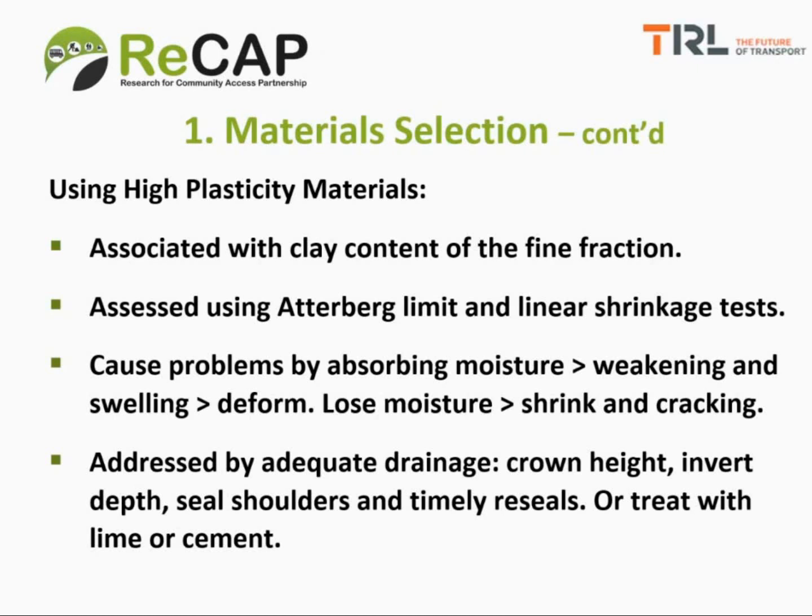Coupled with that is the need to carry out timely reseals in order to correct any cracking which may have started happening on the surfacing. And of course, in some cases, you may have to treat the material with lime or cement.